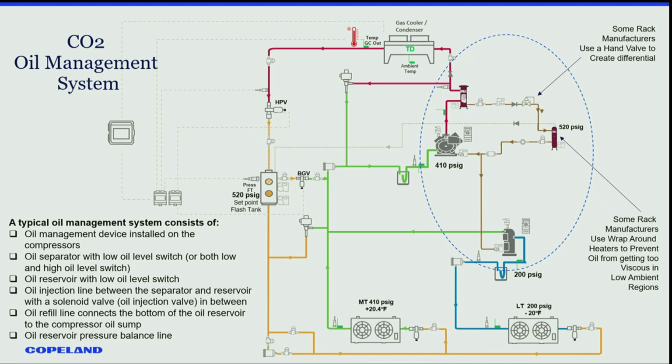But that's important. And the other thing, of course, is that in an oil separator, 100% of the mass flow goes through that oil separator. The purpose of the regulator, to knock it down before it goes in there, is that to reduce the amount of power that you put in the flash tank? Because if you were to just dump 1740, it would have to vent off whatever made the flash tank. Too much. So it's there to knock it down to reduce that load, correct? Right. Outlet pressure regulator to make sure that the pressure on the outlet is maintained to a certain amount. And it's aided by the equalization. Yeah. So you do have all that mass flow going through here.